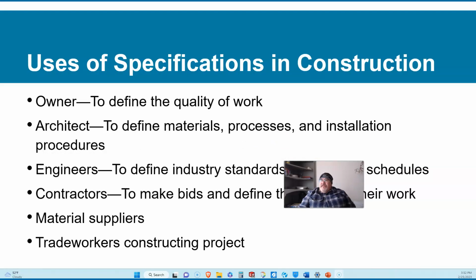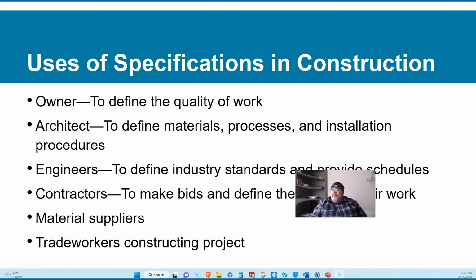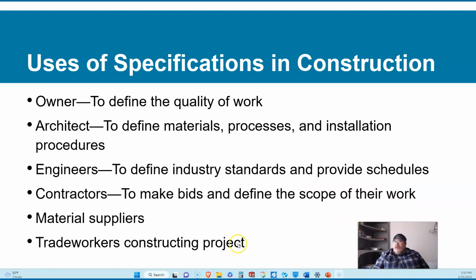Use of specifications in construction. For the owner, it's to define the quality of the work. For the architect, it's to define the materials, the process, and the installation procedures. For engineers, it's to define the industry standards and provide schedules.